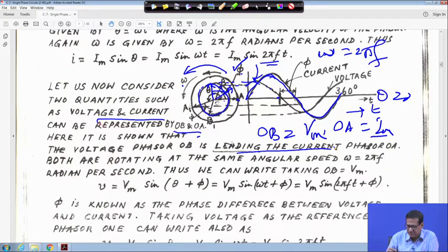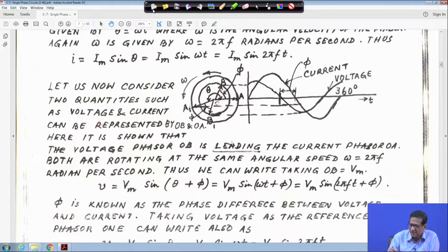In that case, first we have to understand leading and lagging, and then we will come to this. So, first let me clear it. Now, the question is what is leading. Out of these two waveforms, you have to see which one is reaching its peak value. Forget about magnitude and other things: which one is reaching its peak value earlier than the other.